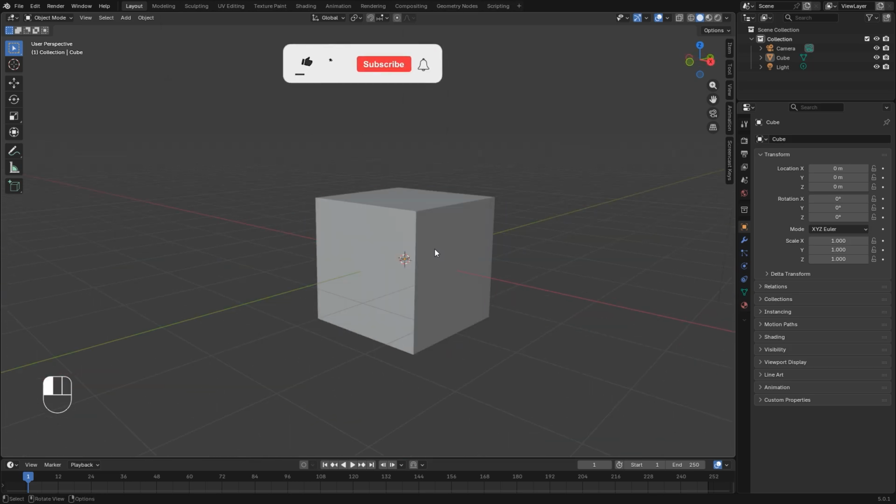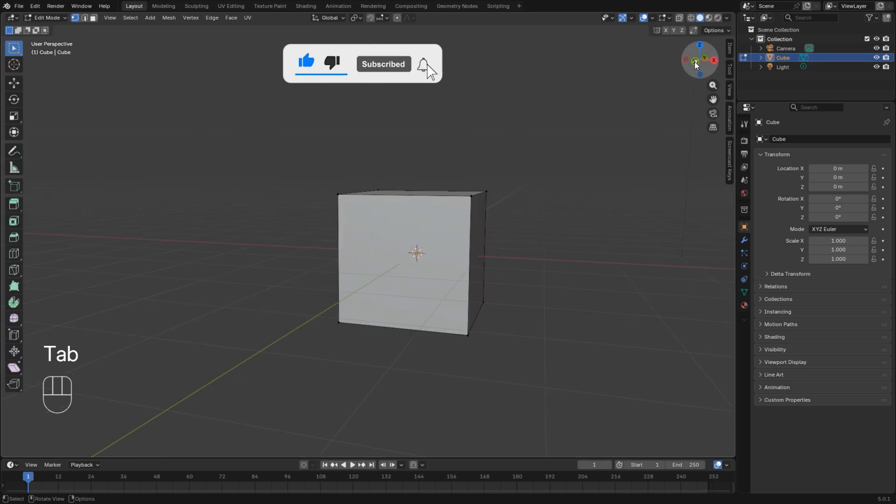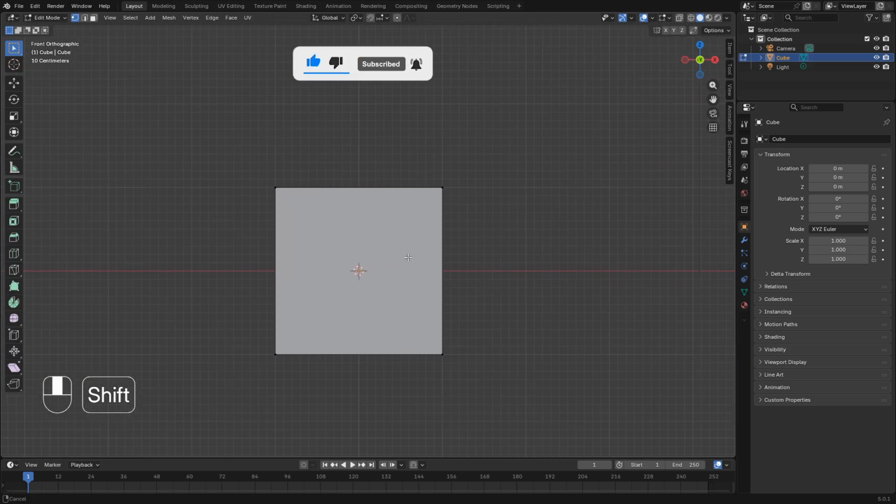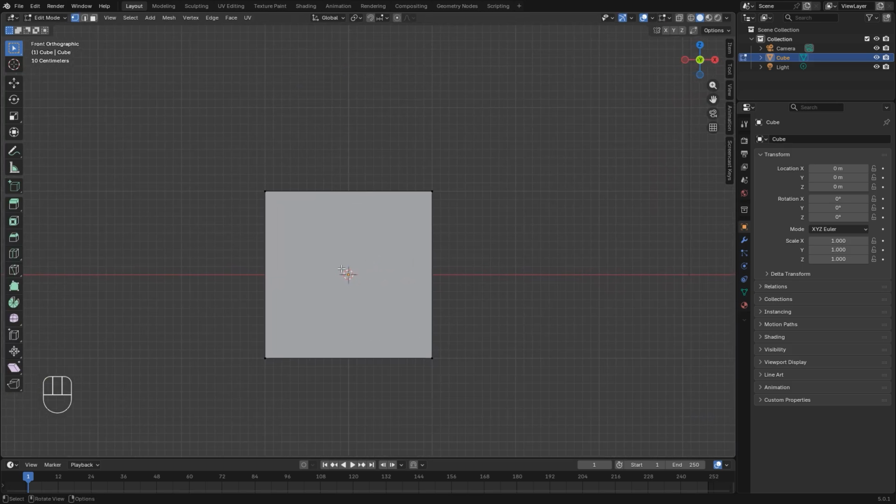Now let's click on our object and press Tab to go into edit mode. Within edit mode, we can start cutting up the geometry or the shape that we have. You can do that by pressing K. Once you press K, you'll see a small knife icon appear on your screen. This means Blender is waiting for you to draw a cut. You can draw a cut by just clicking within your object with the left click, just like this.